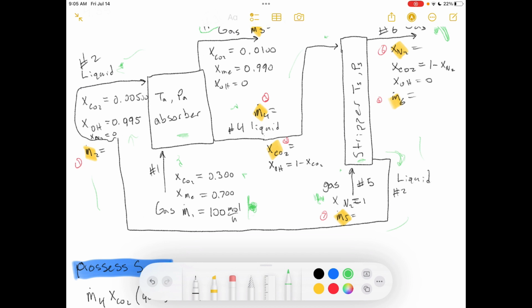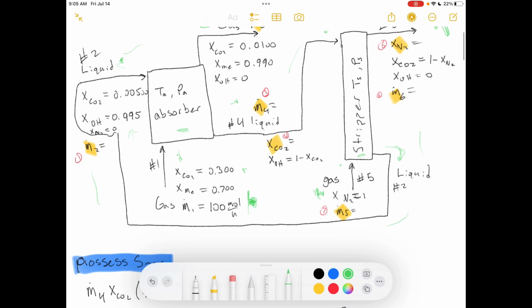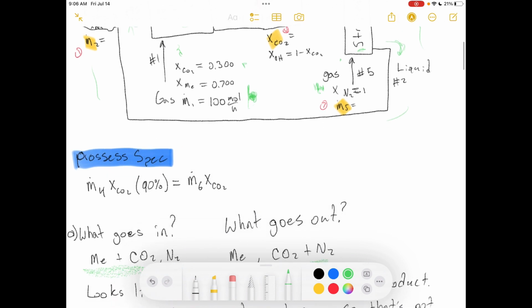And why is that? Well, because there's a natural motivating force due to the density differences in these two streams, for the gas to rise on its own and for the liquid to fall on its own, right? So the gas and the liquid will just separate. You're not fighting against that natural force of the gas. If you were trying to fight against that natural force, you'd probably lose. So when you're mixing a gas and a liquid, you want to make sure that you put the liquid in the top and the gas in the bottom, and then they'll just kind of move through each other. Okay.